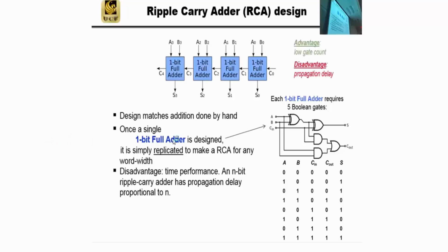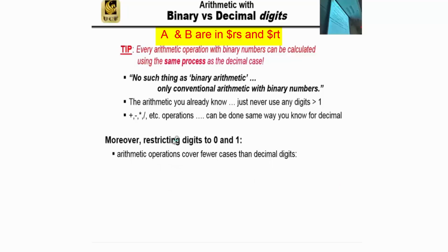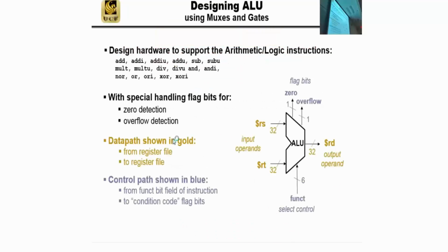and the A and B comes in. Where's A and B in our MIPS instruction? We're adding A and B, so where's A and B? The registers. It's RS, right, and RT. It's the registers. So on here, we're backing up, sorry, but now it's the time to see these. These are the input operands. We take a RS and an RT.